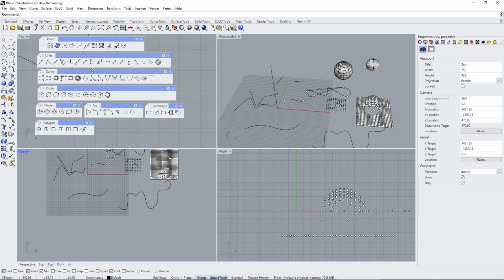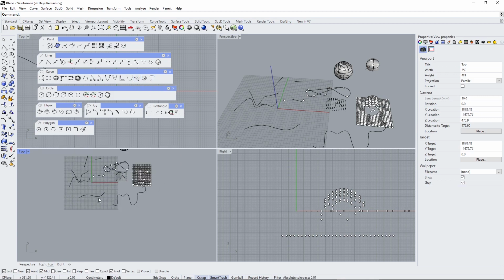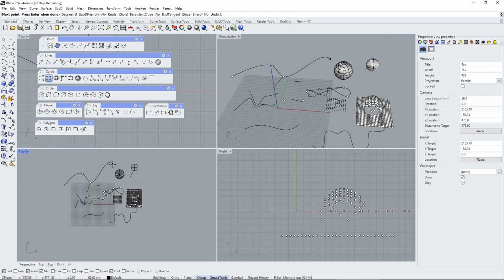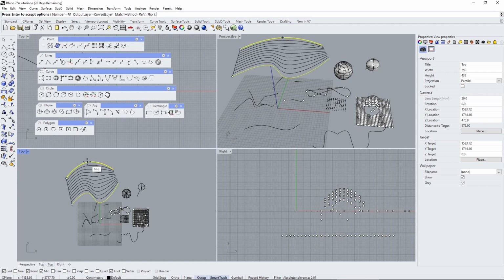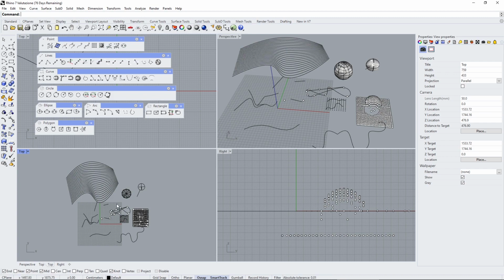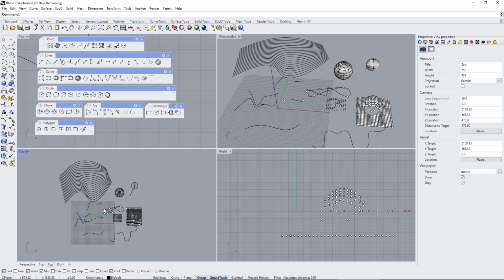For example, here you can create a twin between two curves. This is also one of my favorites. So let's create here a curve and another curve. Okay. And now select the twin between two curves, select the first, select the second, and there you go. Amazing. And you can change also the number here of lines that you want. Again, go through the options all the time because you can find something interesting in there. And press enter, and that's really wonderful as well.